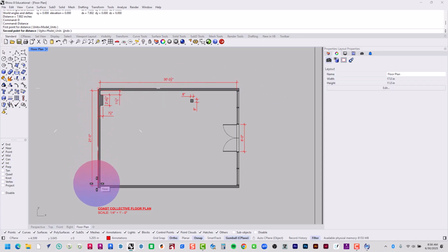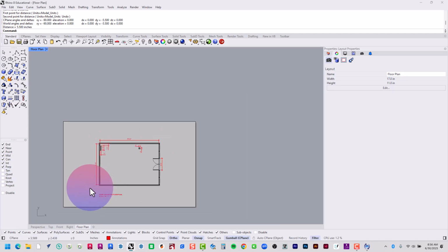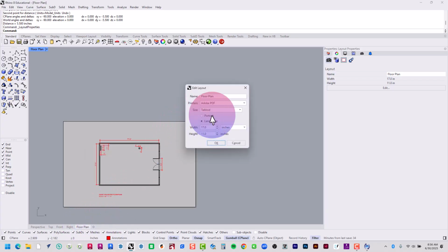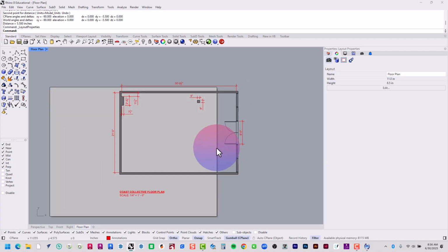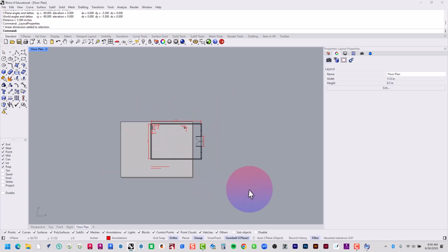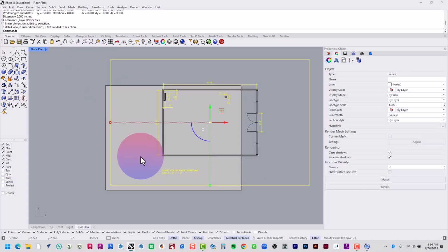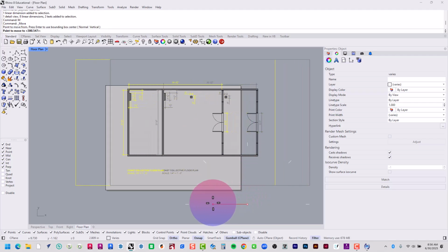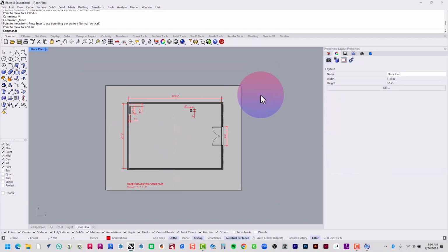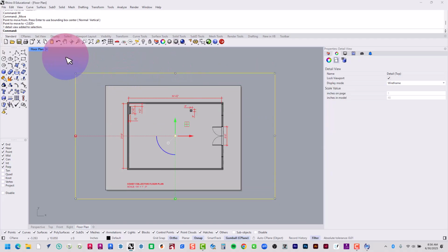And then I'm just going to move it into place. I can actually take these control points. So if I wanted to downsize the actual viewport, I just need to find the viewport, which is like that. Take these control points, move it down, snap to my perpendicular point, take these control points, move it in there, take these ones, move this in here, take these ones and move them in here.